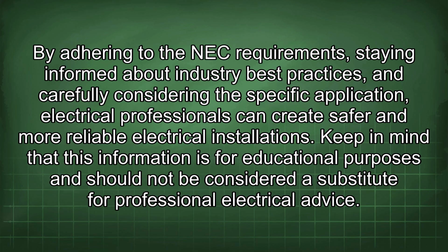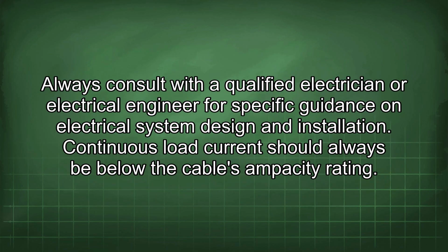Keep in mind that this information is for educational purposes and should not be considered a substitute for professional electrical advice. Always consult with a qualified electrician or electrical engineer for specific guidance on electrical system design and installation. Continuous load current should always be below the cable's ampacity rating.